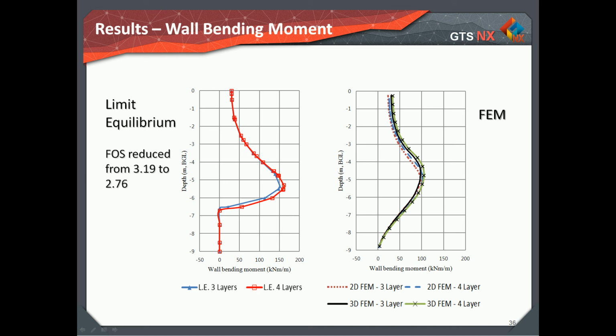The wall bending moments show less proportionality, especially for 2D and 3D FE models, which predict the maximum wall bending moments to be approximately 30% lower than limit equilibrium method suggestions. The 3D model correctly suggests the worst case scenario occurs at middle columns. Thus, the graphs for the 3D method are based on this specific location.